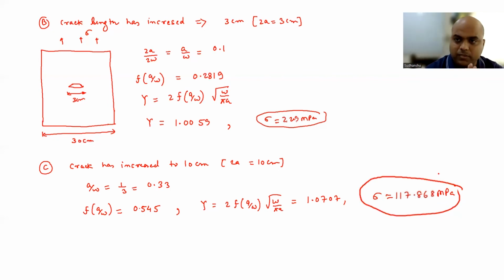Second problem. Okay. So we have understood the concept of fracture toughness, how it varies with thickness. And I also mentioned that at a particular point, the fracture toughness or critical stress intensity factor becomes equal to plane strain fracture toughness, which is the material property. Okay. So I will quickly tell you about the ASTM standard of plane strain fracture toughness measurement, and in the next lecture we will talk about how to determine plane strain fracture toughness.